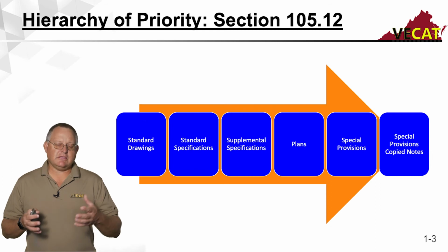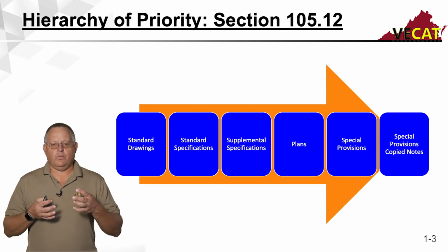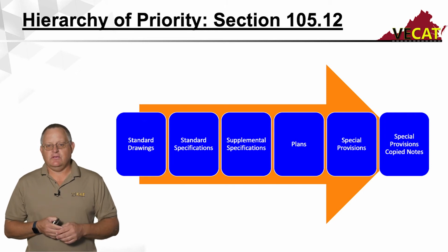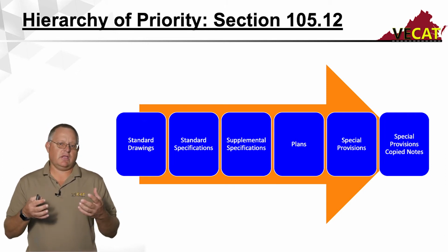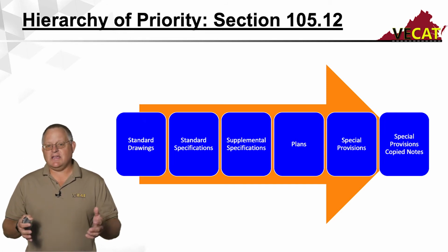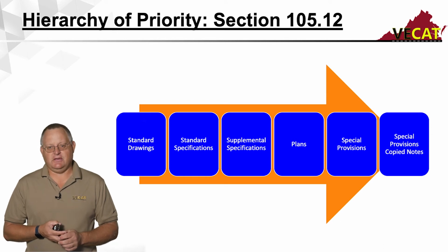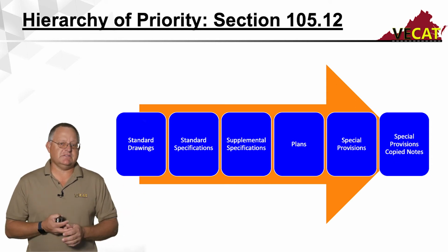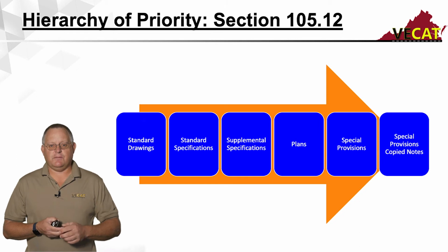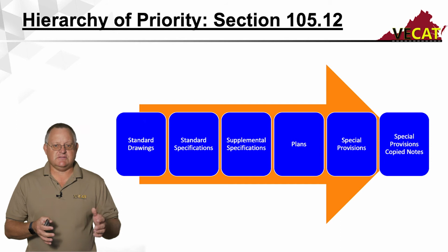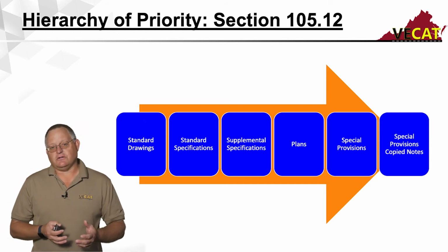So when we look at the project itself, what is the most important is that special provision copy note. So when your company gets a project, a good question to ask is, are there any special provision copy notes specific to this project? Could be sampling, but it could be there's some differences in the testing results. So if you're a plant level 2 technician, maybe the voids in total mix changes for a specific material, you need to know what those are.